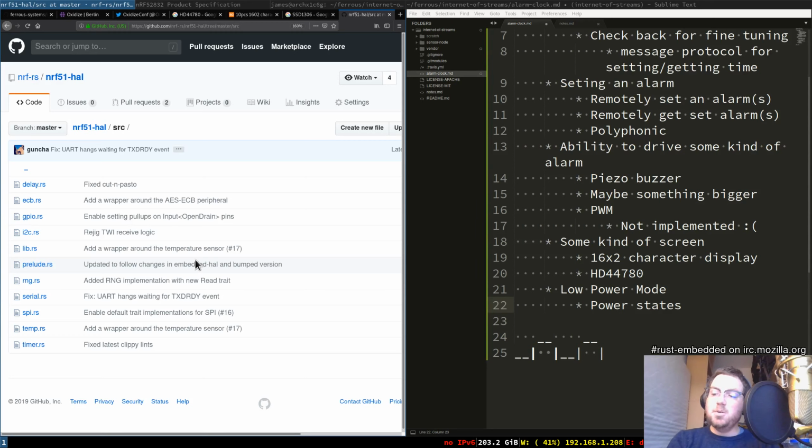Okay, so there are kind of two ways to implement an MP3 player on the NRF52. You can implement it on the microcontroller itself, where you manage everything in software, where you do your MP3 decoding and playing music and stuff like that. But that means I need to have a lot of things. I need some kind of flash storage, like an SD card, because this only has 512K of flash, which means I could put 30 seconds, 15 seconds of song on there and play it over and over again.